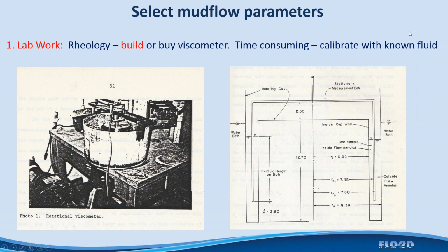This is rather time consuming, and you have to calibrate it with a known fluid, like glycerol, which is about as high as you can get, although today you could do it with maybe some asphalt or other types of high viscosity samples, but you would have to have a commercial viscometer too, maybe alongside this, in order to get some more highly viscous fluids to calibrate with.